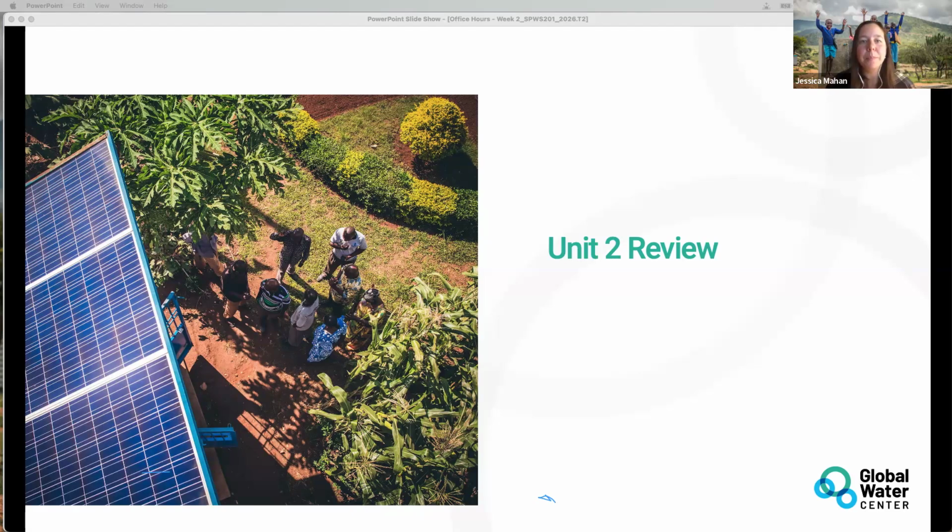So maybe the one that's nearby, we know, for example, it could do 6 meters cubed per hour, and that's its maximum. And so maybe we decide to start at 4 with the hope that we can go up and have a little bit of room to go above that 6. Maybe our borehole can do a little less or a little more, but maybe it doesn't do quite as much, so we start lower.